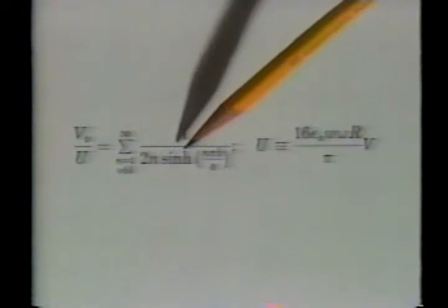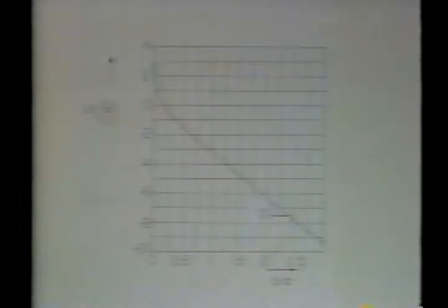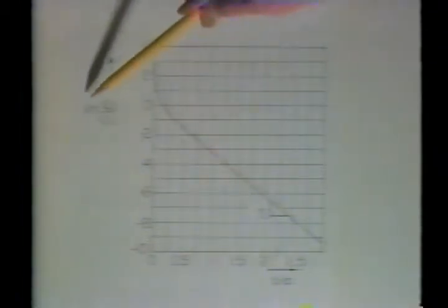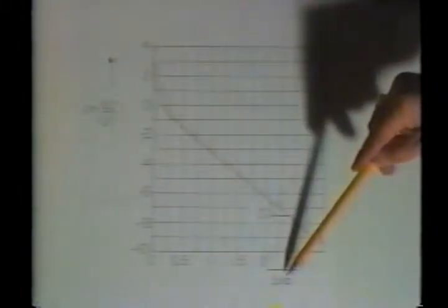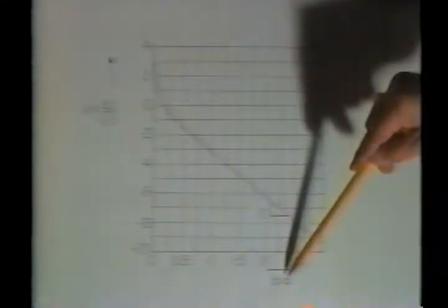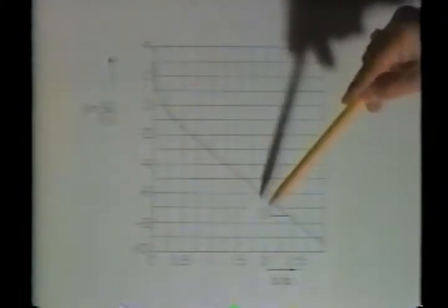As the lower electrode is withdrawn, its potential decreases exponentially. The output voltage decays with electrode spacing because charges induced on the input electrode have their images either on the side walls of the box or on the output electrode.